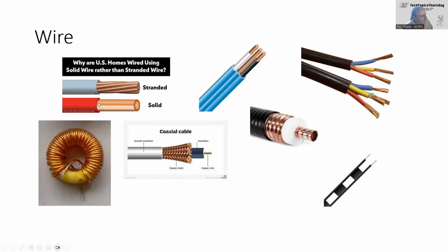And if you strip away your insulation and make a little nick here by accident, that's also a weak point where the wire can break. So typically, they use the whole wire to connect it somewhere mechanically and then strip off the insulation just to make the electrical connection. And I've found with some antennas and some other wires that I've just had in a case or in a cart going back and forth for breakfast every morning.